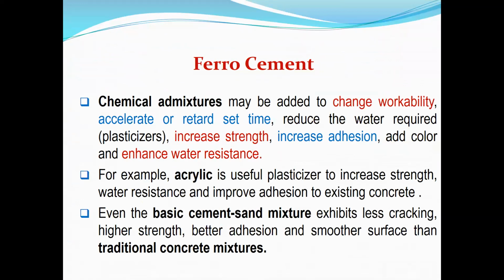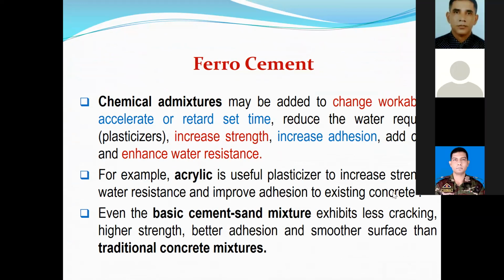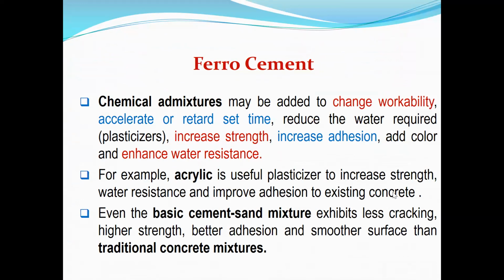Sometimes chemical admixtures are added to change the workability. Workability means the ease of working with the mixture. They are also used to accelerate or retard the setting time, and to reduce the water required for getting the strength. To reduce water, sometimes plasticizers are used.